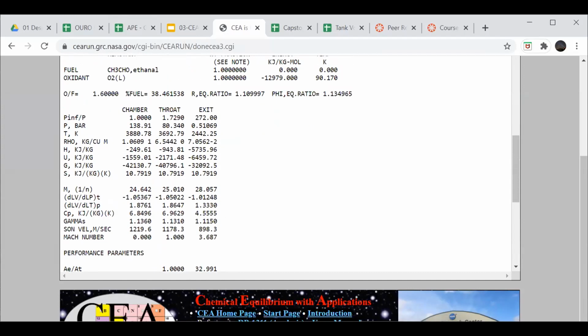So where is it? There's the exit. Actually, you can see it there. You have the sonic velocity and the Mach number in the bottom line, that first block. If you multiply those together, you have your exhaust velocity. And then, because momentum is conserved, your thrust is equal to your chosen total mass flow rate times that exit velocity. Arun, you're jumping ahead. This is next week's lesson. Yeah, I know, but that's where it comes from later.